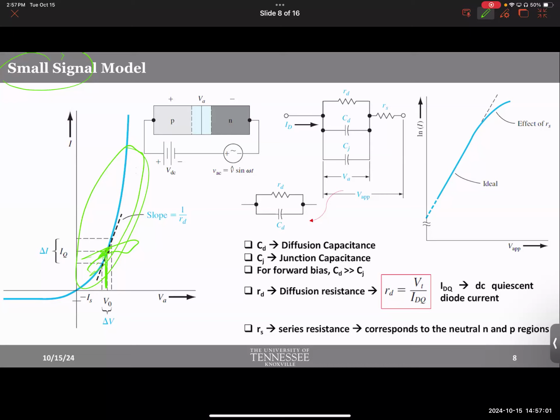So you have to choose where we are going to operate the diode. We're going to operate it at 1 volt. Sure. Let me figure out how the resistance is in the vicinity of 1 volt. Are you guys all with me so far? So remember, it is being designed for a DC operating point, say 1 volt. We choose that DC operating point because at a different operating point, the resistance will be extremely different from each other.